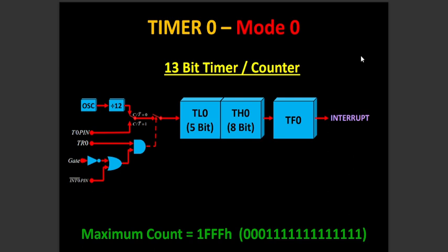the TH1 register is incremented by 1. When TH1 overflows from FFH to 00H, then the TF1 bit of the TCON register will be high and it stops the timer/counter. For example, if TH1 is holding F0H and it is in timer mode, then TF1 will be high after 10H times 32, that is equal to 512 machine cycles.